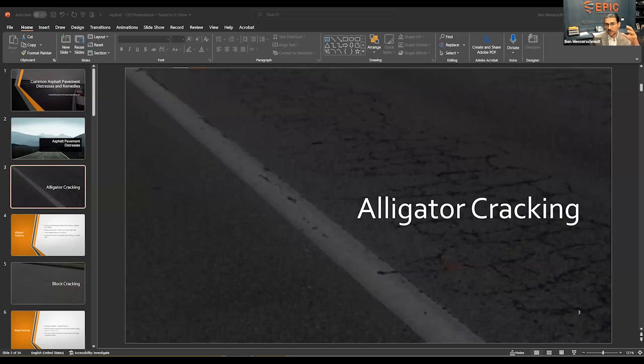So you'll notice these pieces are also going to be less than 2 feet long. There's really going to be small little breaks uniformly connected. The biggest reason why, like I said previously, is going to be load based. The biggest loads you're going to experience are obviously going to be within the wheel path, unless you have some localized distress for whatever reason. If you're on, let's just say, an equipment site and you have asphalt pavement, and something large was dropped on there for whatever reason during the course of construction, or a staging area potentially for a contractor within an HOA, for example, that could also be a cause of this.